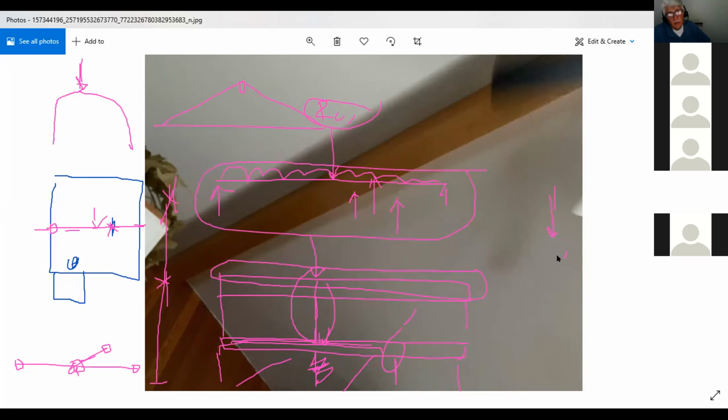Because that's what is actually supporting your rafters, you understand? Yeah. So that is a structural beam. It's not aesthetic. They finished it. It's nice. It's probably a BC fir beam, you understand? And it's probably a 6 by 12 or 6 by 14. It's a big beam, trust me, okay?